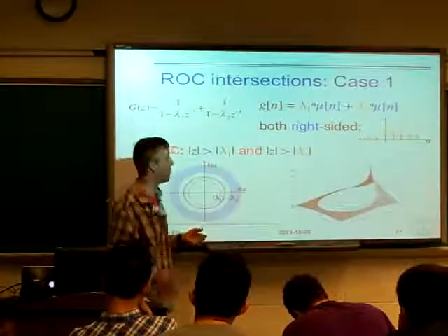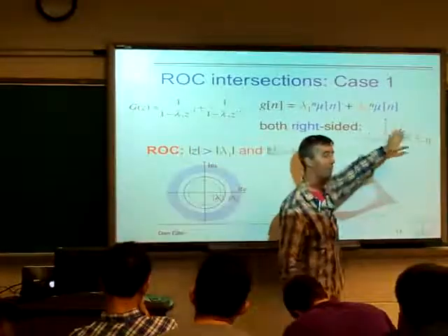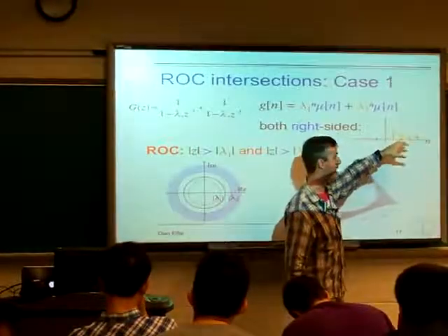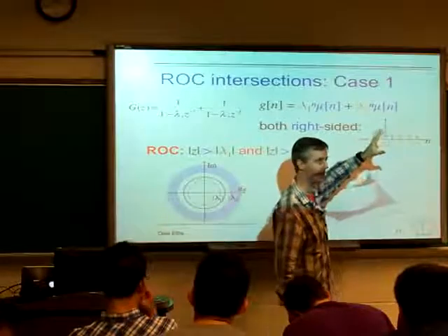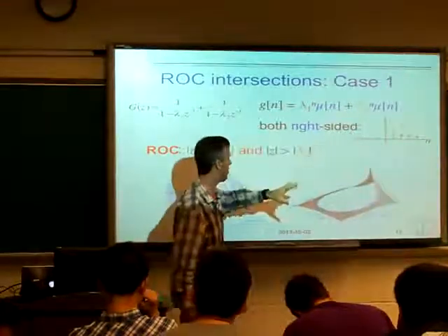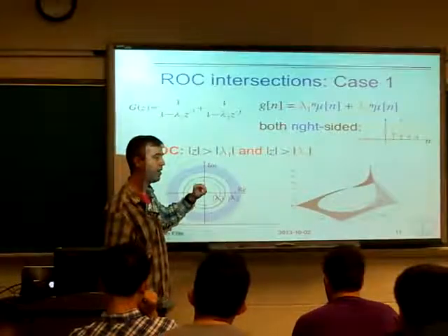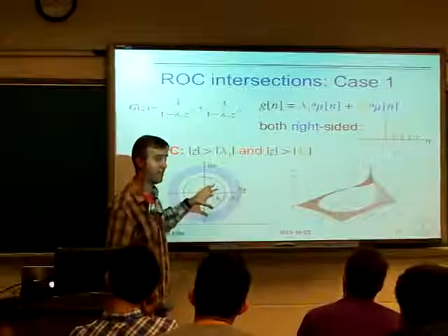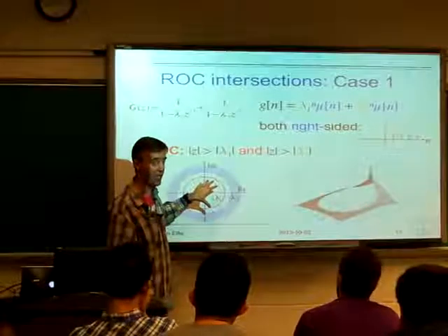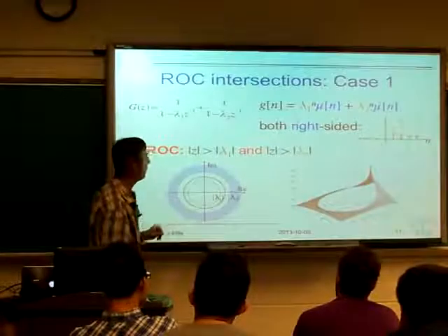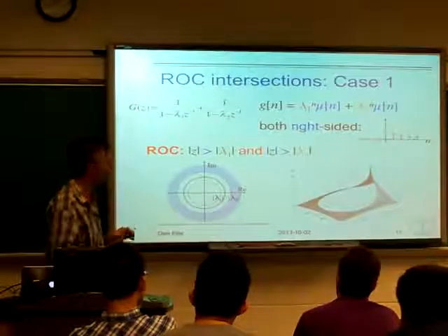That's saying the same thing, that this kind of sequence is not something we like to deal with in discrete time because it's not bounded. The Fourier transform method is not going to work for us. It's the same as saying you have a closed form expression for G(z), but it's not valid on the G(e^jω) values that you care about. So that's how that all plays out.